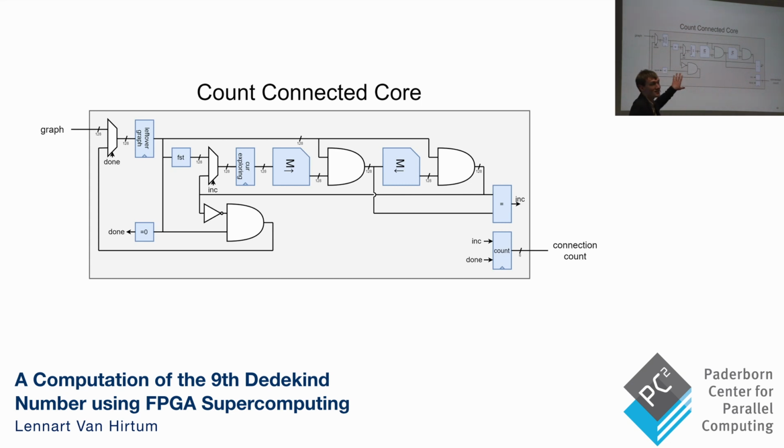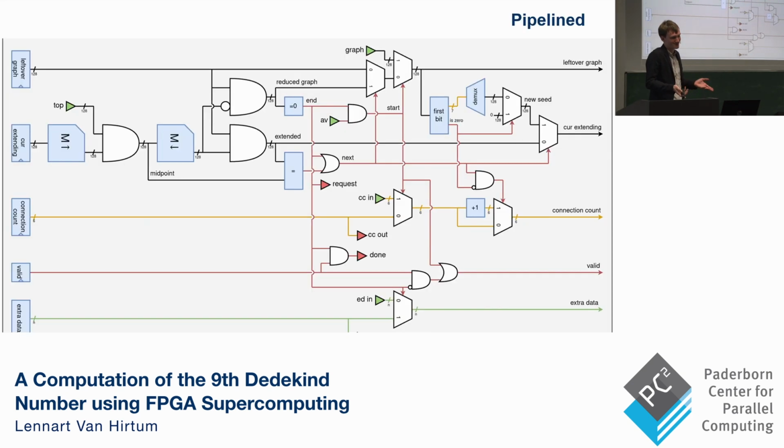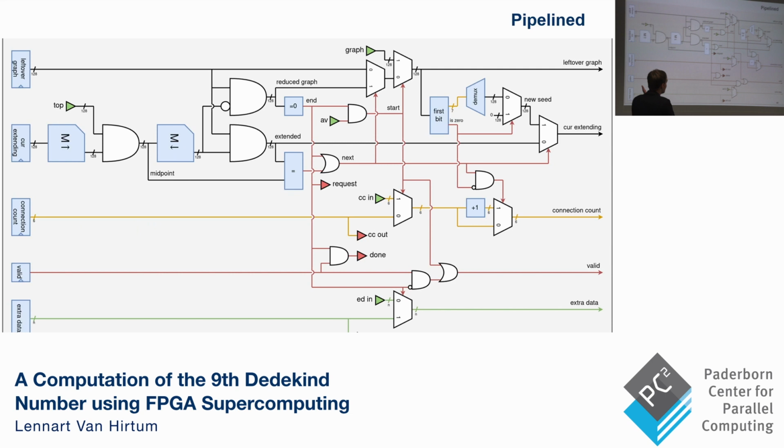Now, of course, this is a really nice block to show, okay, the hardware works. We can implement it simply in hardware. But it's not going to run fast. And so this is where this diagram comes in. I spent a few days painstakingly drawing this. And this diagram has a very special structure, namely wires and signals always travel to the right. And so here, this looping structure, I've made it kind of implicit, so the signals come out, and they go back in the registers on this side.